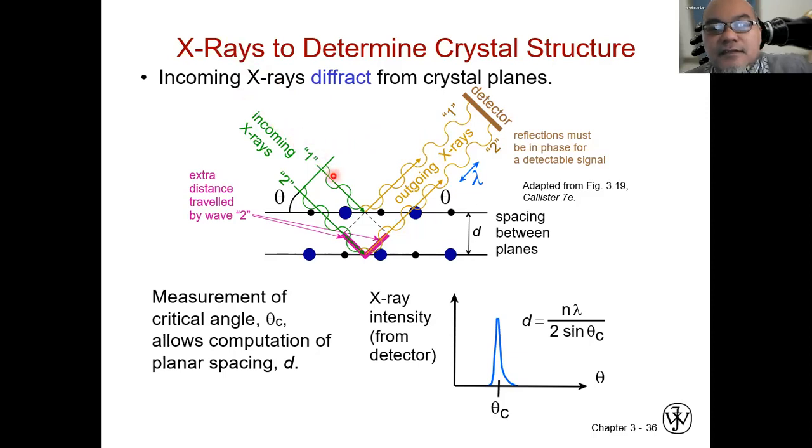They use X-ray at a certain angle, and usually this angle can be varied from 0 until a certain angle. Whenever the diffraction occurs, which will be indicated by this kind of peak, that angle will correspond to the D, the spacing between the planes of that crystalline solid. That is incoming X-ray 1, incoming X-ray 2, then outgoing X-ray 1 and outgoing X-ray 2.